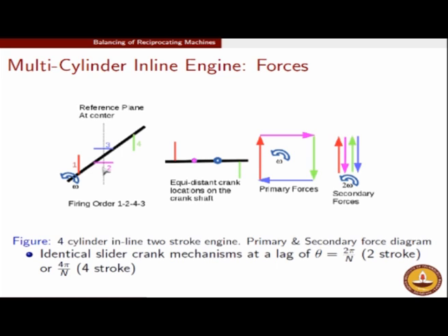In the secondary, since you have a 2 theta sitting in your trigonometric terms, the angle between 1 and 2 in the secondary will not be 90 degrees but double of that. So the angle will be 180 degrees. Similarly, the angle between 1 and 3 won't be 90 degrees, it will be 180 degrees. And lastly, the angle between 1 and 4 won't be 180 degrees but 360 degrees. So 1 and 4 will now get completely aligned and 2 and 3 will now get completely aligned.